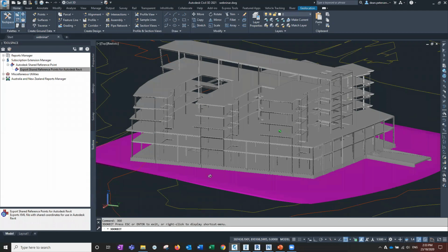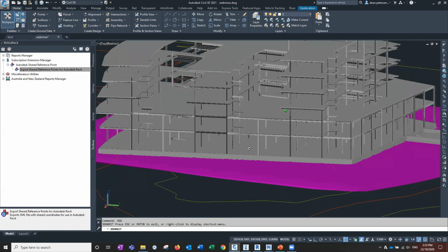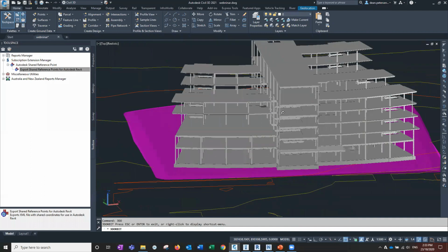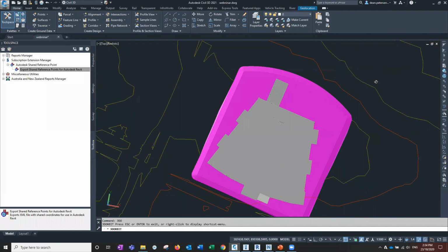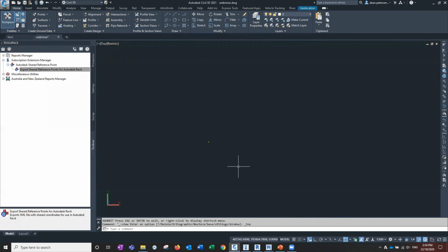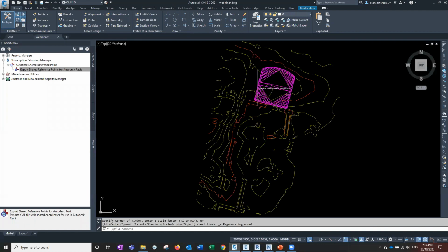If we've got places we know we need to get surfaces into or out of, we can check the levels are right. We don't have depressions in there. All that stuff can be done in Civil 3D, and it works very, very nicely. And obviously there's little lag, which is the whole reason for using that NWC. I'm going to go back to my 2D view. Once I've finished, you can actually snap to those coordination models as well. Zoom extents, and I'm going to end the object isolation to start working with it again.